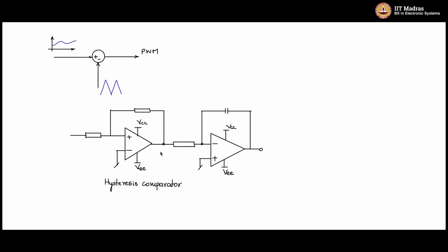If this is negative, current is going to flow in the other direction, and the capacitor will charge with the output side positive. And the output of this I will connect to this input point to give the oscillation effect. So now this is a positive feedback triangle generator.